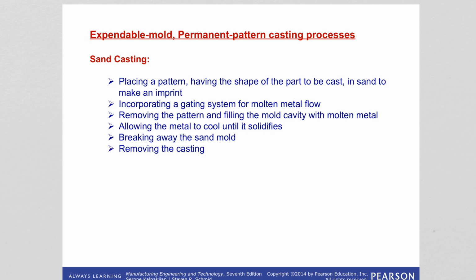It makes an imprint on the sand, and we incorporate a gating system for molten metal to flow, because we need to introduce the metal to the mold.